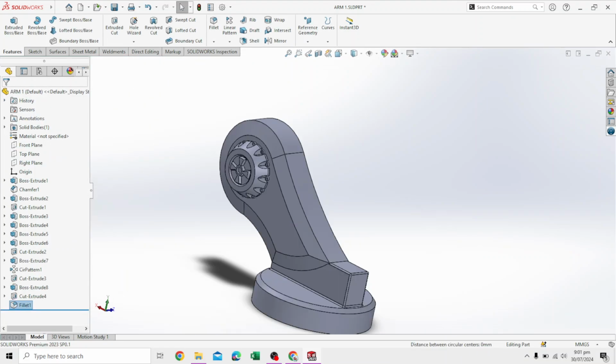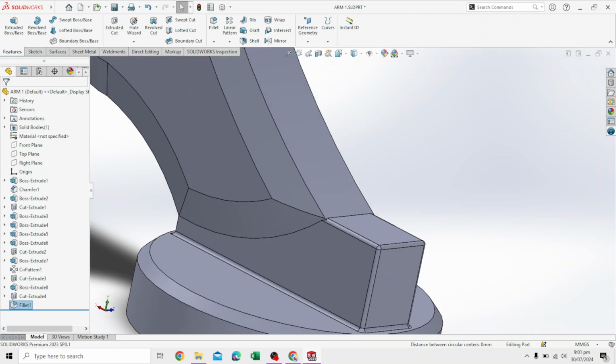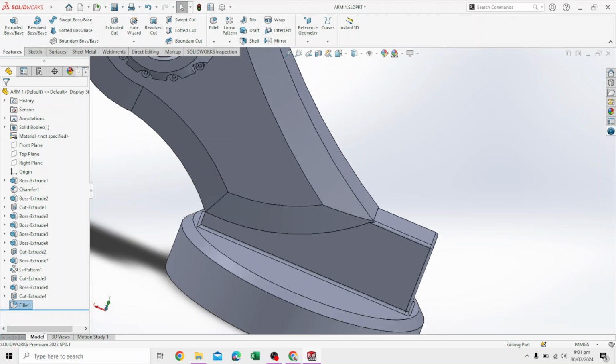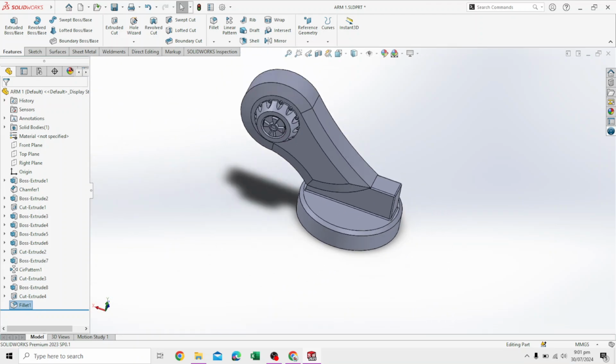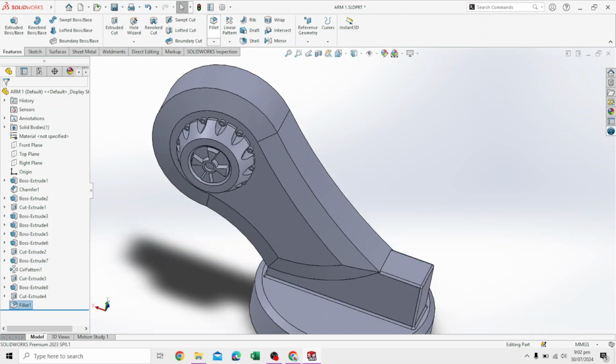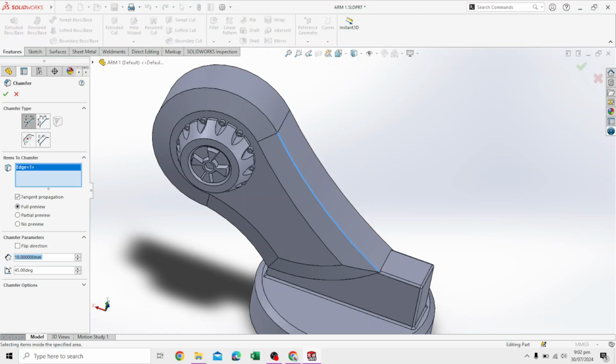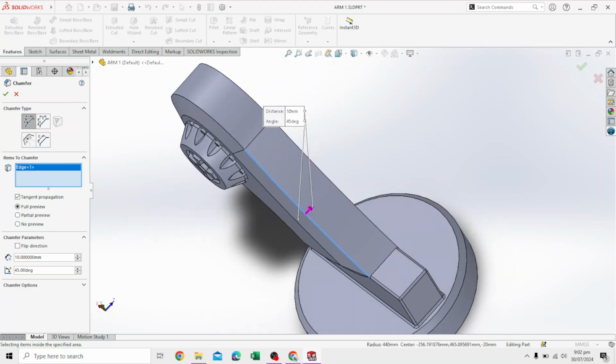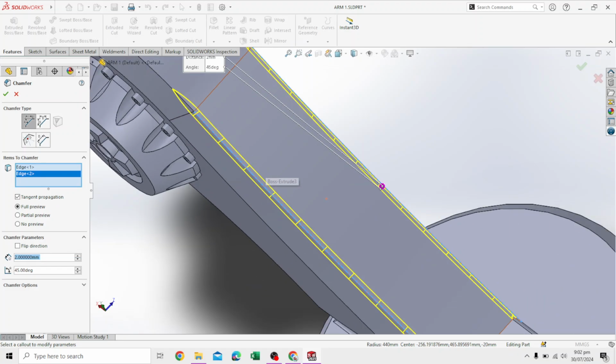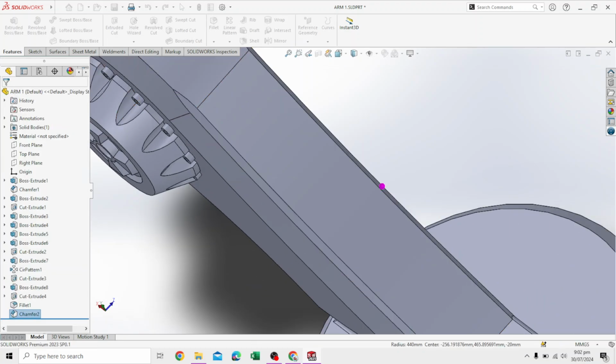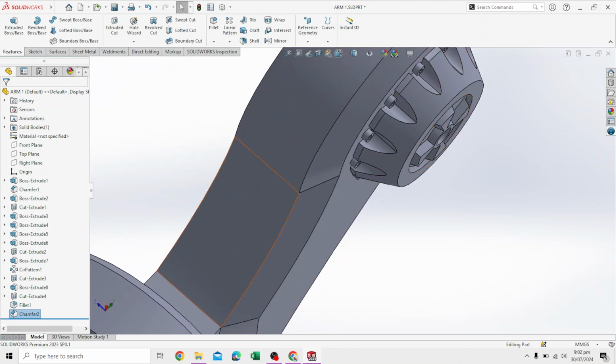After we fillet this, in this section, obviously it's not going to be a highly detailed section, but we will do this. Go to chamfer, in this fillet drop down menu, and select this as well as this, and apply the value. If you double click in this, it selects the whole thing, and then you just overwrite that. It should look something like this. Say okay.